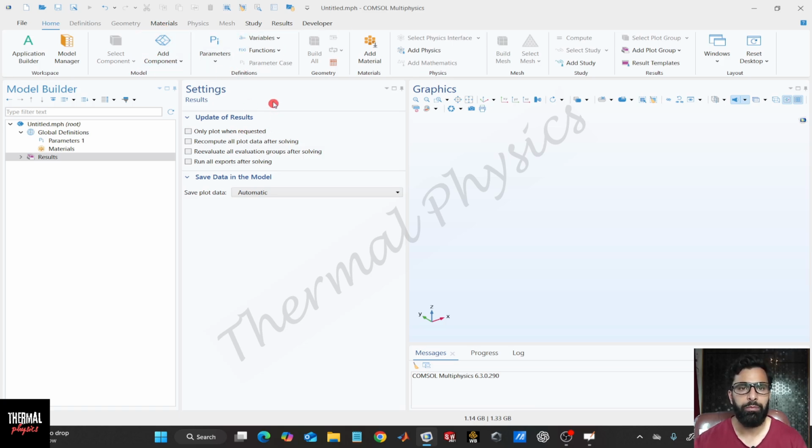For example, say we go to the materials section here, which is under the home tab. Material has one option, add material, because mostly when we make a model, we have to add the material. We click here, it opens the library, and we search which material we want to add. We write the name of the material in the library search bar, and we click add, and it gets added. This is what we need for basic models and basic tutorials. That's why this has been placed here.